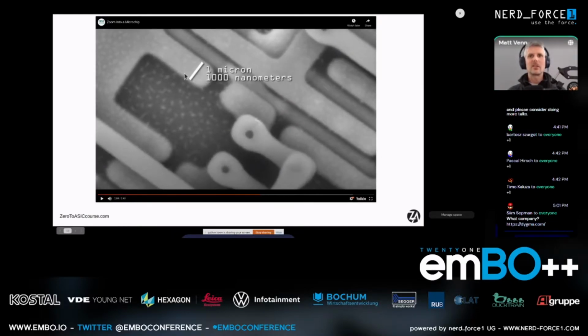So in this particular technology, the width of the gate in the MOSFET is 1,000 nanometers. And in the SkyWater open source PDK, the width of the gate is 150 nanometers. So we're about 6 times smaller than this. And that's where we are with the open source PDK.